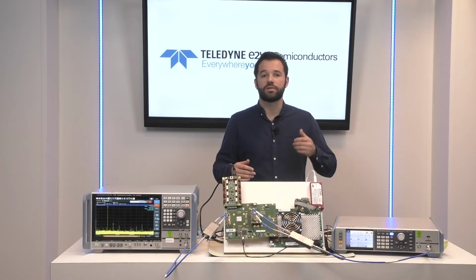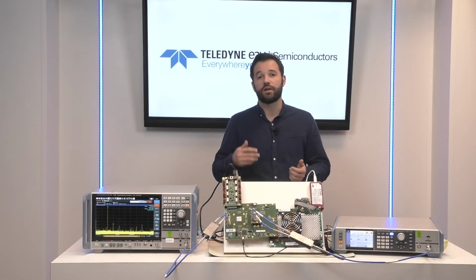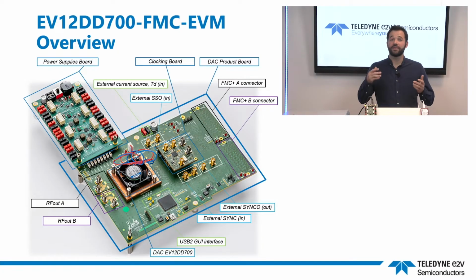An FMC Plus board compatible with commercial on-the-shelf FPGA development boards and FPGA design examples are now available to accelerate your development. Here you can see an overview of the EV12DD700-FMC Plus evaluation board, giving access to the 2 DAC RF outputs using a double-width FMC Plus standard connectors interface.